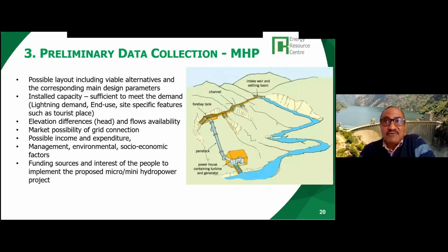So you have to find ways to estimate what the flow available would be. And when I talk about the flow available, you have to be able to find the variation in different months of the year. In 12 months, how would the flow vary? Because when you have the rainy season, the flows obviously increase, but when there is no rain, the flows decrease on the rivers. The minimum river flow is an important parameter that needs to be gauged in the beginning. For that you can use some very simple flow estimation techniques. I will talk about it a little later.